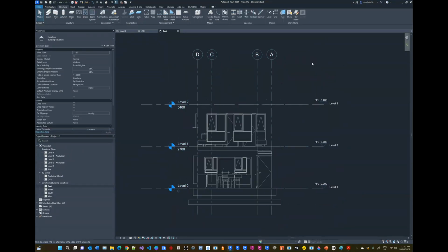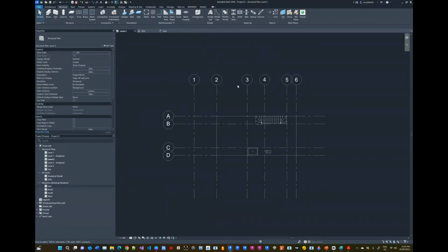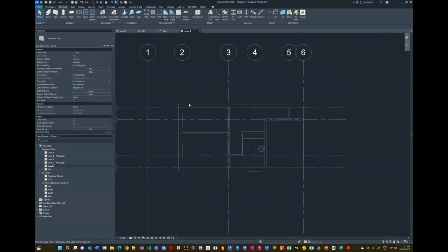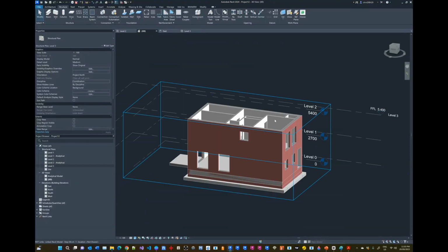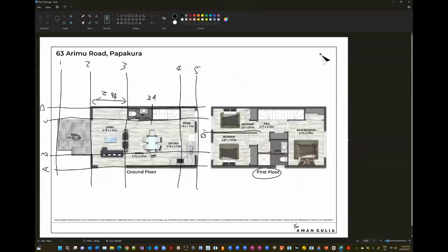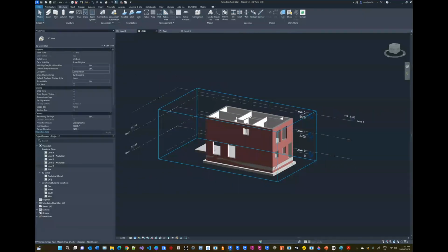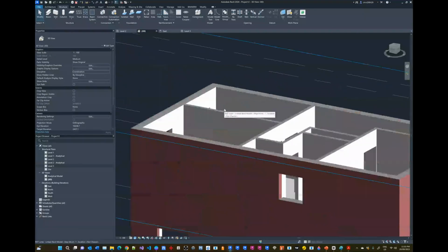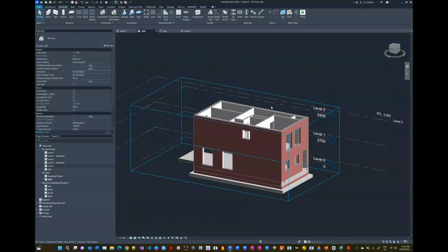We can create grids by selecting these from our plan view, but I'm not going to go into all of that detail. Basically, what we would like to do here is to just see that underlying model, and we want to create a roof truss that's going to sit nicely across here. Now remember, in our architectural model, we said we don't really have the information on what this roof is supposed to look like. We're going to assume that there is some kind of a monospan single pitch roof running across here. And we're just going to estimate or guesstimate that to be sort of a 10 degree slope, and we're going to base our model off of that.